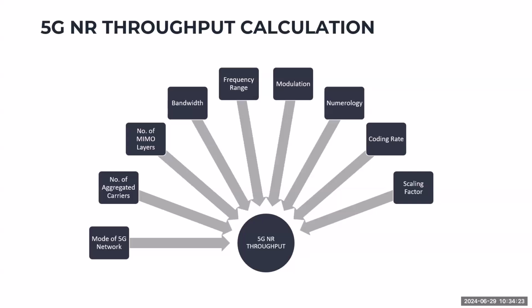Okay, so probably the scaling factor of 700 is okay, but if you're at the cell edge, you're very far from the cell site. So even if we use a high scaling factor in the calculation, if you are already on the cell edge, it doesn't mean a thing anymore, because you are too far. Okay, so your calculation is no longer accurate. And of course, the overhead for control channels. We will discuss that, okay?